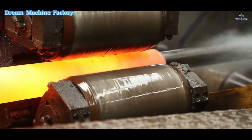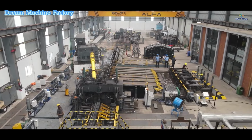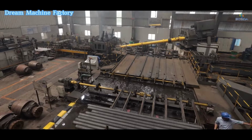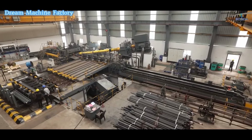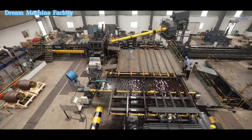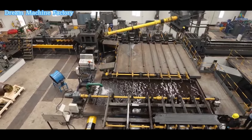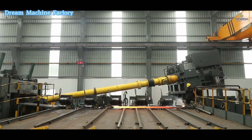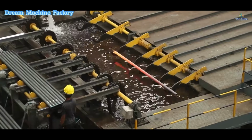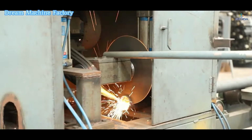The hot piercing mill's main advantage is its ability to produce seamless pipes without welding, making it ideal for high-pressure applications where welded joints might fail. After the piercing process, the hollowed tube may be further reduced in size or elongated through elongation or rotary extrusion. In addition to the physical shaping of the metal, the hot piercing mill ensures that the surface of the pipe remains smooth and free from cracks or flaws, which is critical for maintaining strength and durability.